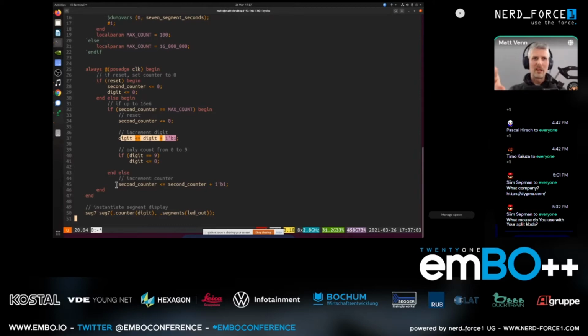So you could make that one counter, it takes up a certain amount of area, and then if you want 100 times the throughput, you just multiply that by 100. You've used 100 times the area, but now you're doing 100 additions every clock cycle. So you can see why people spend so much time on custom graphics cards, because we're accelerating a specific thing that we need to be extremely parallel.